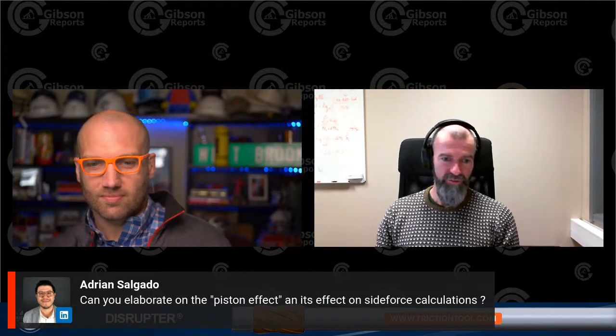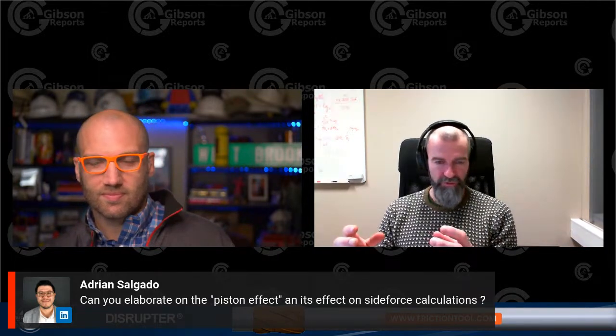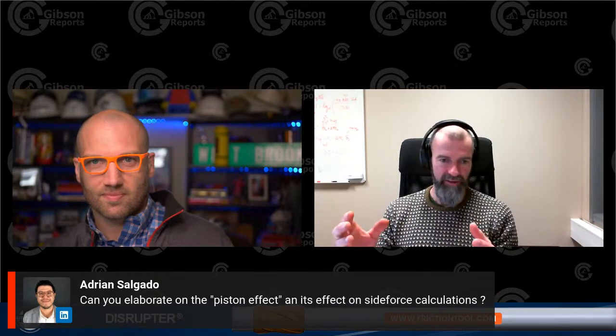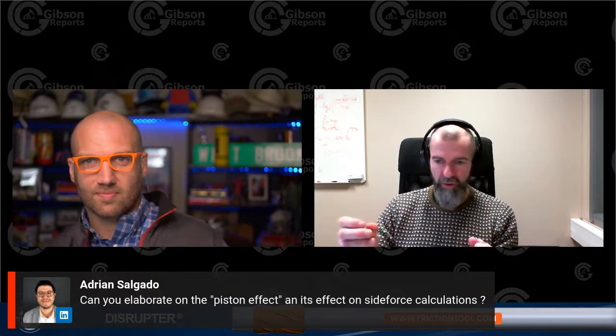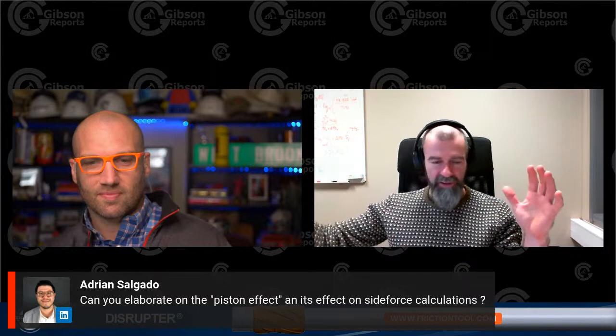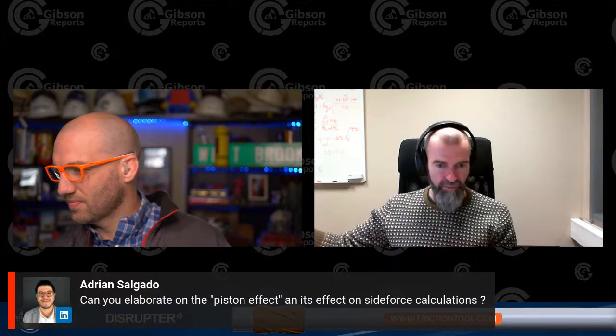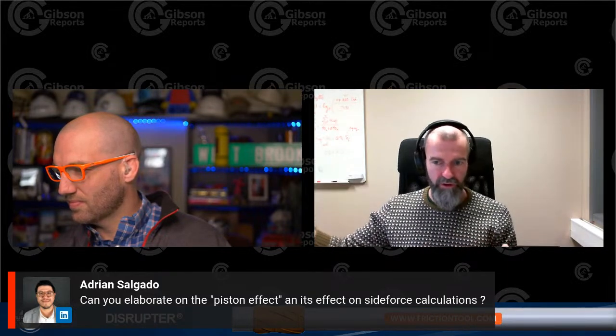You can take all the small forces, from mechanical to hydrostatic to hydrodynamic, add them to your calculation, and then sum it all up at the end. Or if you take a small portion, sum it, take another small portion, sum it, and do it that way, you should end up with the same thing. The hook load shouldn't change.